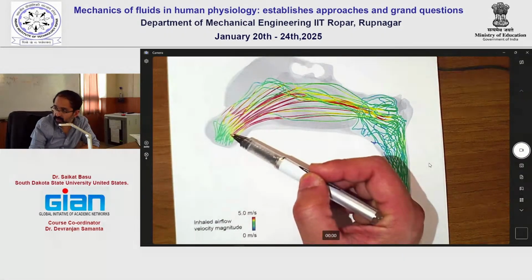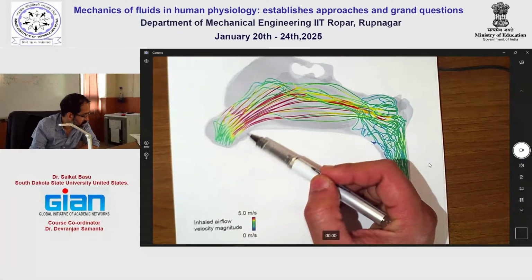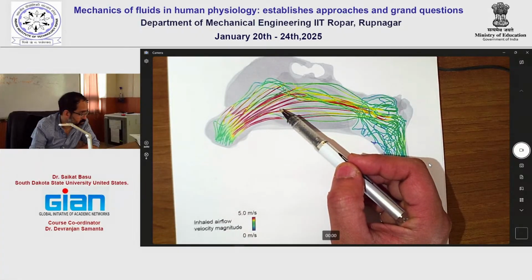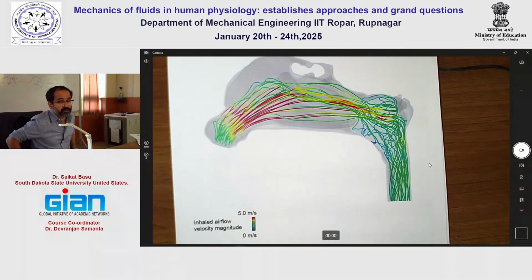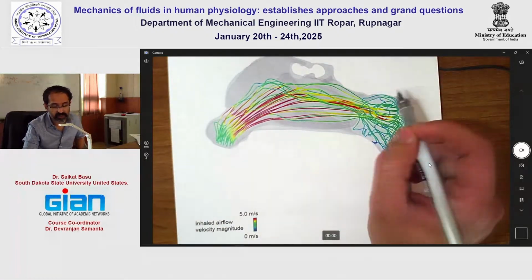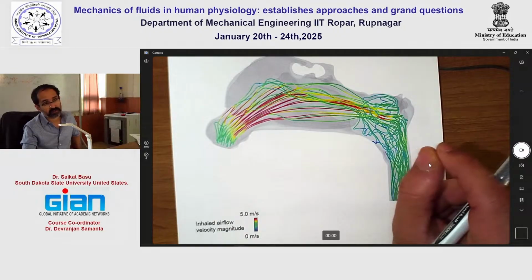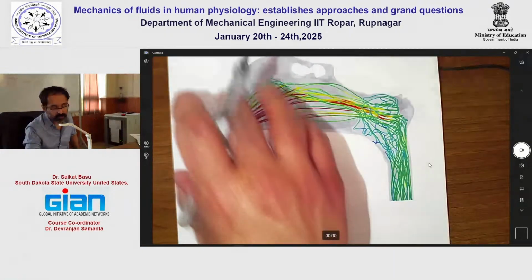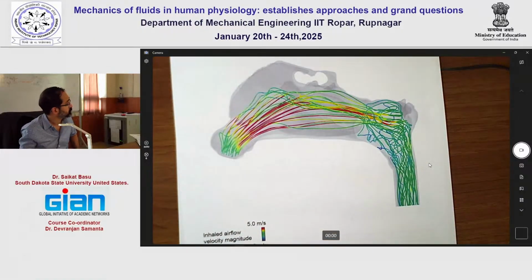So on the order of 1 meter per second, let's assume. And the maximum it gets is 5 meters per second. Now, if you remember one of the problems, I had assumed the flow to be 5 meters per second. Here is the justification for this. But also with 1 meter per second, as we found, even if the flow is slower, the problem that we were trying to solve was how long does it take for a 100 micron particle to deposit, and we saw that the time interval is so short that it is going to deposit in the anterior parts of the nose.